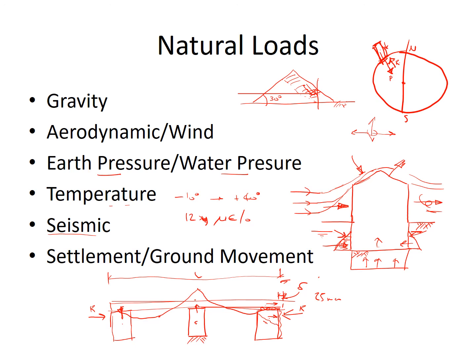Now, if that central support is on ground which is not capable of providing this reaction load without deflections, if we take it to the extreme, for example, if we allow this central support to deflect significantly, so sink into this ground here, then essentially we lose all or some component of this reaction at this point.